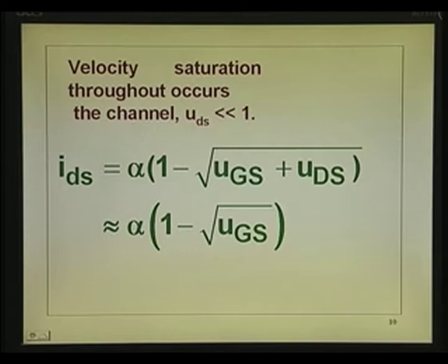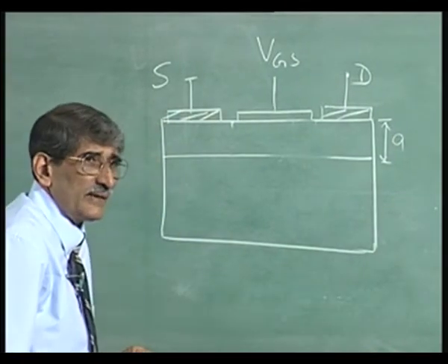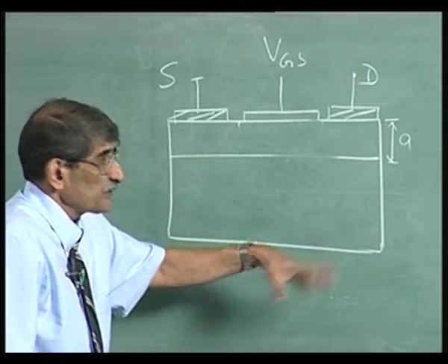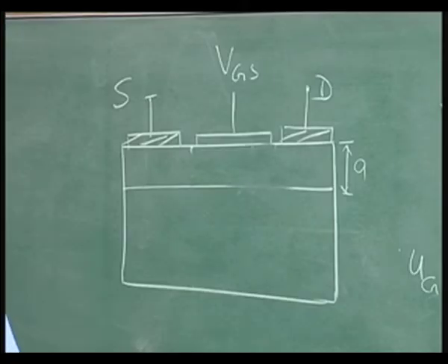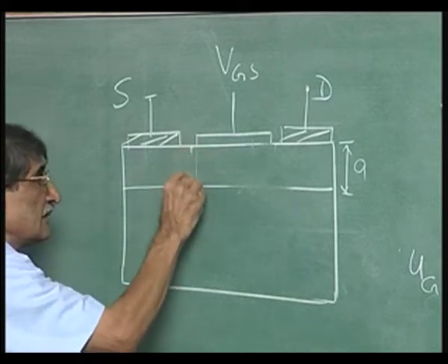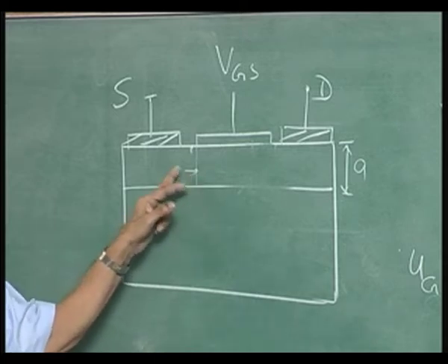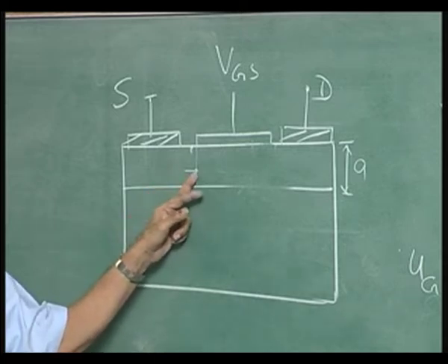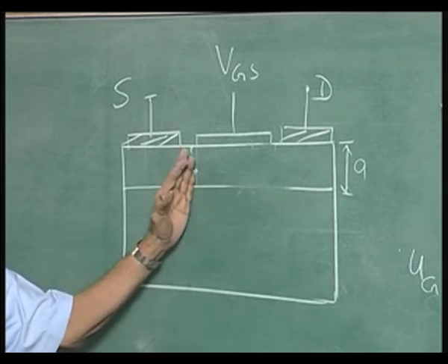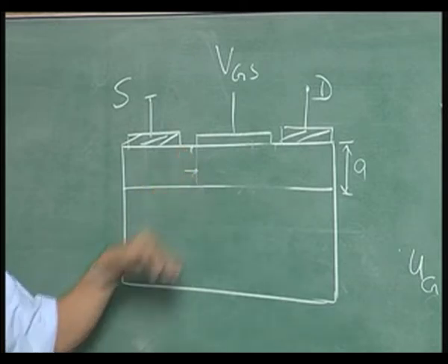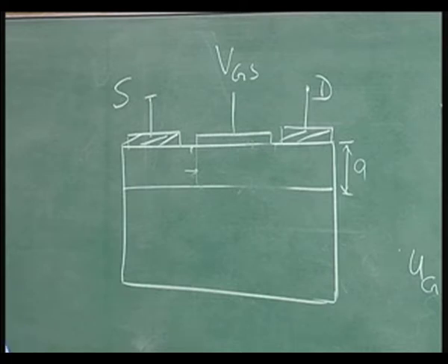Let us put that down here now. Things get a little bit bleak, because we are looking into an extreme situation. The electrons, when they enter itself, have reached velocity saturation. They already acquired the velocity saturation. They are not just getting into this portion, they are getting from the inner portion. If that is the situation, once they reach this point, if there is velocity saturation, what will happen to the depletion layer width afterwards?